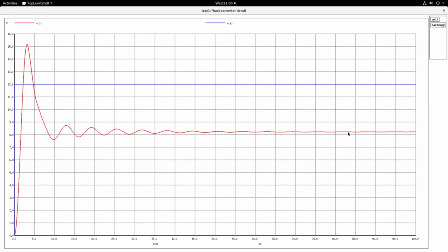You have the duty cycle around 75%, and you can calculate and find out what is the input output relationship, and authenticate it with theory. And also, if there is a deviation, why is there a deviation, what are the non-idealities which are causing the deviation, all these things can be studied and understood.